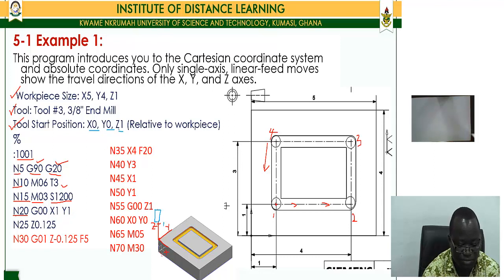So when we give it a rapid go to X1, Y1, it is also going to carry the last Z coordinate, which is the Z1. So X1, Y1, Z1, it's going to move all the way up to the position which is X1, Y1 here, but it will be hovering on top. It will still be at the top because the Z position hasn't changed.